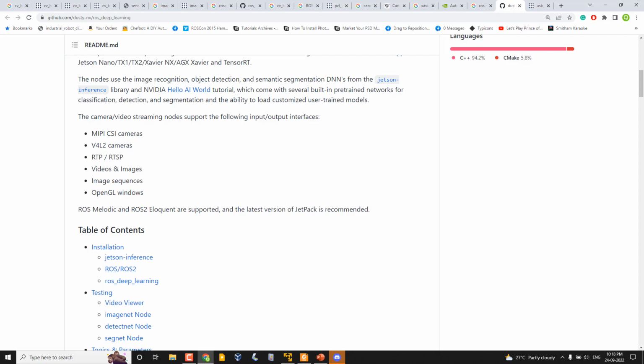The difficulty that I'm seeing is obviously the RAM. In Jetson inference, if you are using the NVIDIA API for doing the detection per model, for a single model there is an API for doing the detection, but that function itself takes about 1 GB. That is the main function which loads the TRT model into the RAM. Using that function, you can give the CUDA converted images to it, and it will do the detection.